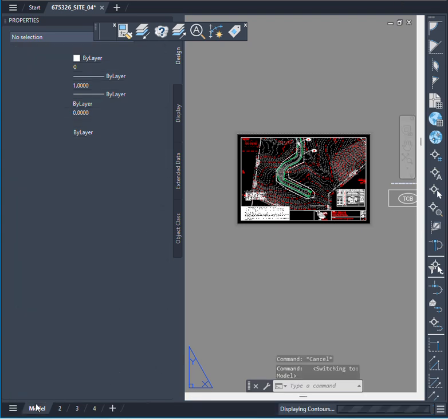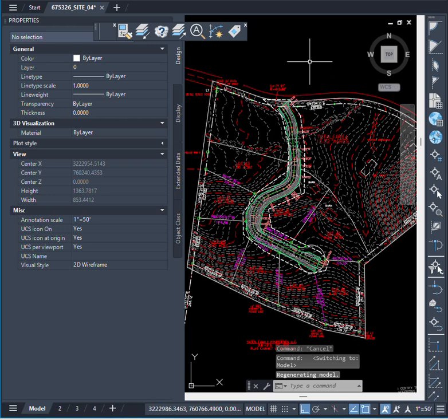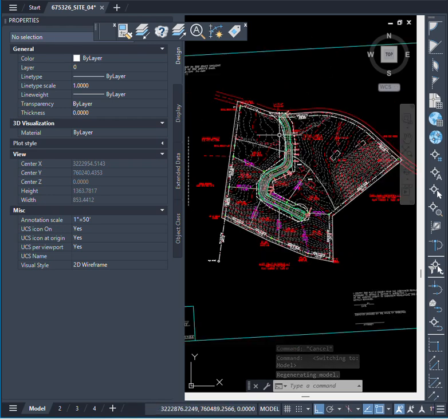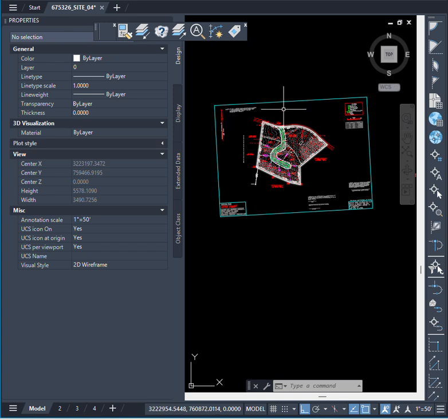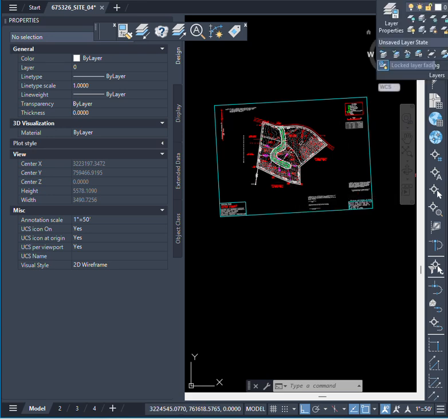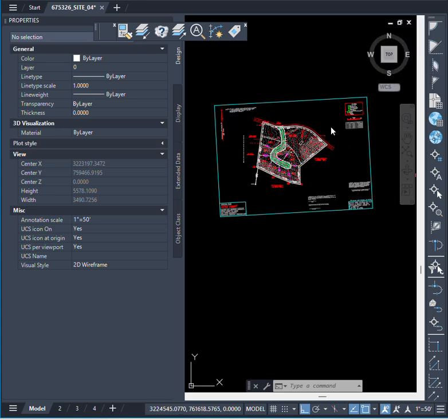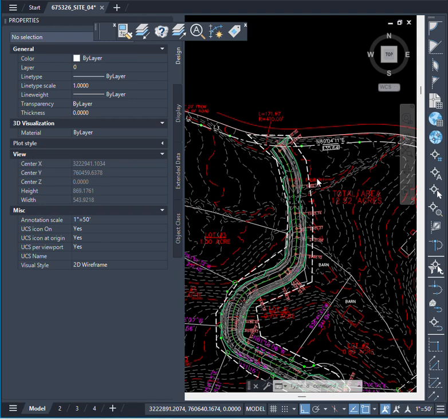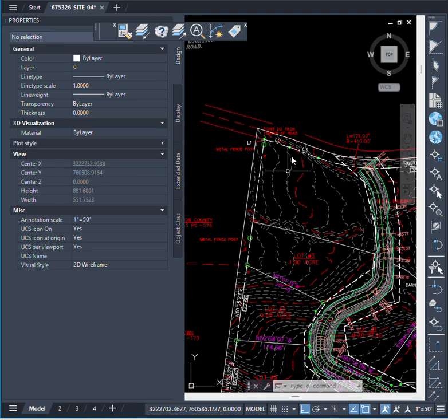And this is a pretty common issue for the type of work we do, because we tend to start off on single sheet projects working in model space, and it doesn't really click how an annotation scale would work. But as long as you set it up this way, it will work correctly. I think what happens is people will get a survey and the existing contours won't look correct. So they'll start changing things.